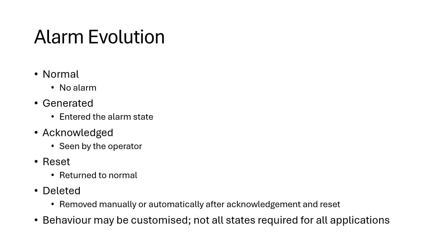In that case, the alarm would return to normal as a result of the operator doing something. But it's also possible an alarm might occur and then reset by itself, maybe because of automatic control of the system, which generates the alarm and then takes action itself automatically. Or maybe it's an alarm which occurs and then goes away because of some other natural reason. So sometimes the reset can happen by itself, sometimes it can be a result of operator action.